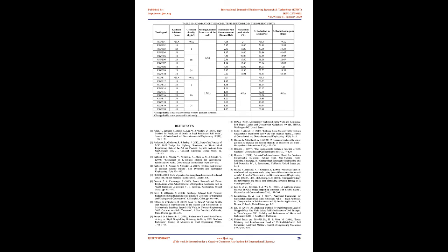B. Wall face movements. Wall face movements of geogrid reinforced soil wall models were evaluated through image analysis for various cases with varying density and thickness of the geofoam. Figure 8 shows the variation of normalized wall face movements with normalized height.